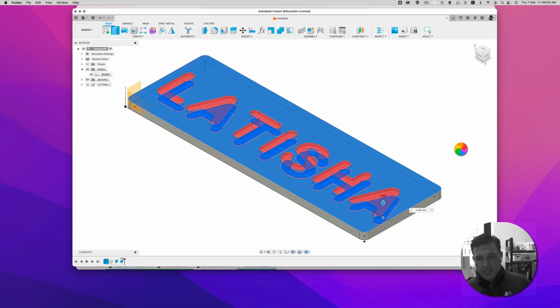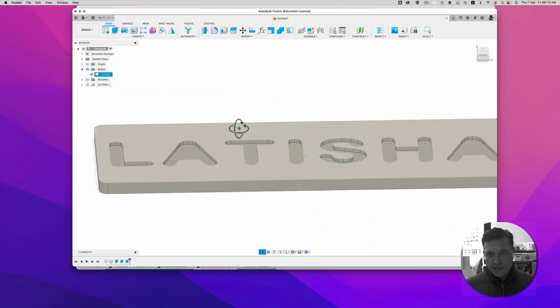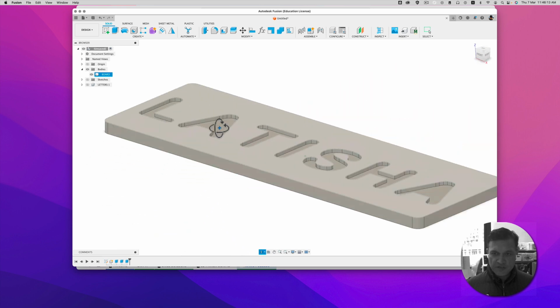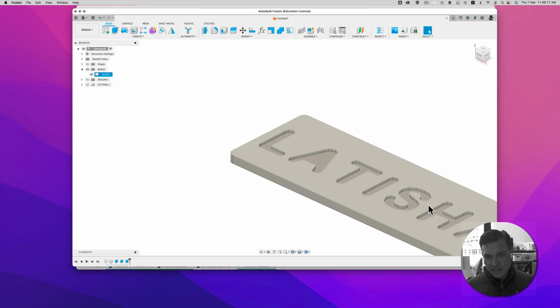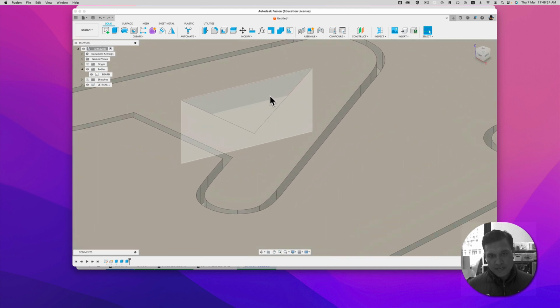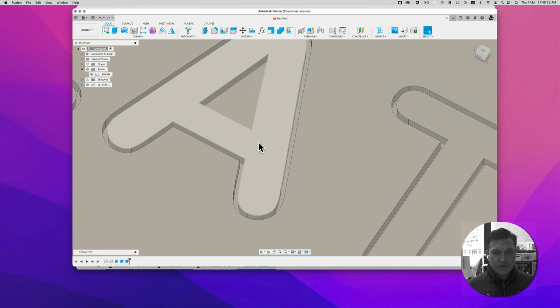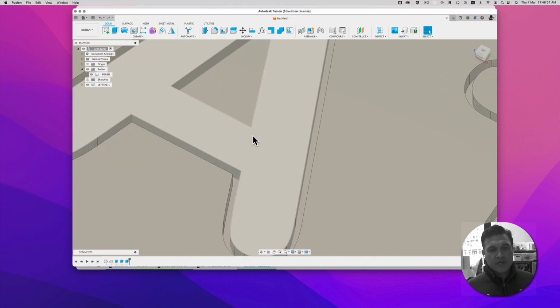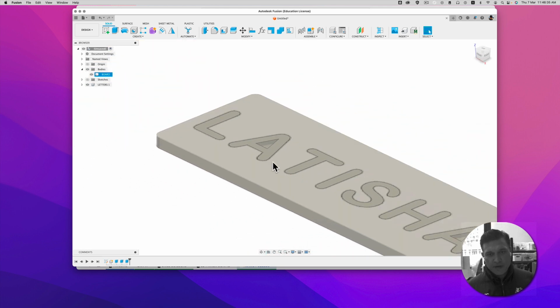And now you'll see, I'll turn off the sketches to make that a bit easier to see, we have cut out the offset of the letters, and we have removed the islands, in this case for the letter A. And if I turn on my letters there, you'll see it means that we have a nice space around the letters, and there's no island here to interrupt the placement of the letter into its little parking space. Okay.